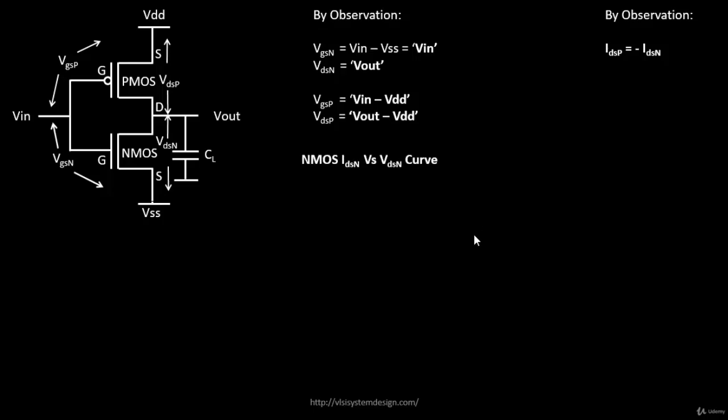So first of all, we'll start with the basic and simple one, where some time back we had done some SPICE simulation on getting the IDS versus VDS curve for NMOS. Okay, we did that in the past, where we actually tuned your gate to source voltage at different points, and swept the VDS, the drain to source voltage, and got some drain current equation. So it looked something like this. I've just taken one example over here. So it looked something like this.